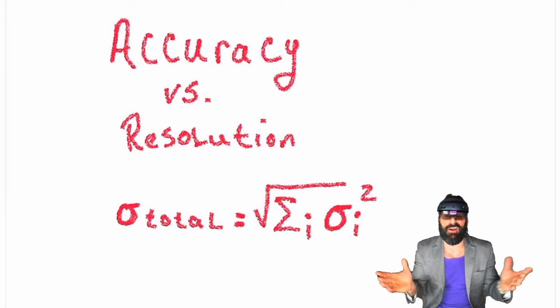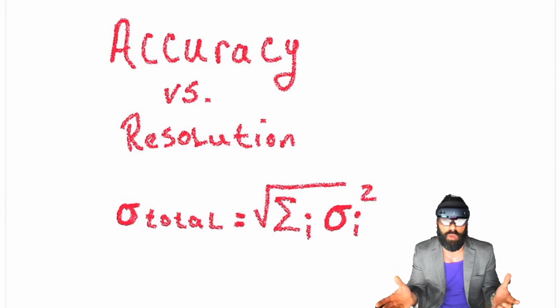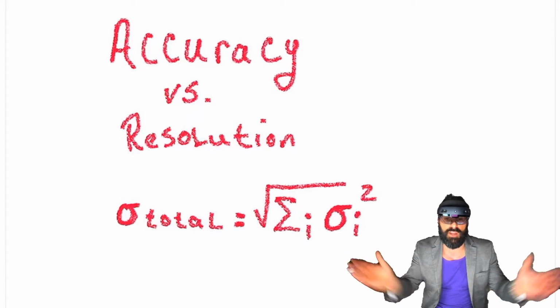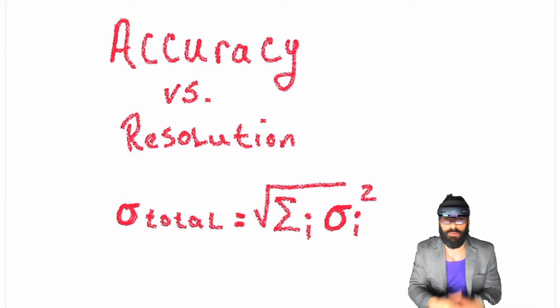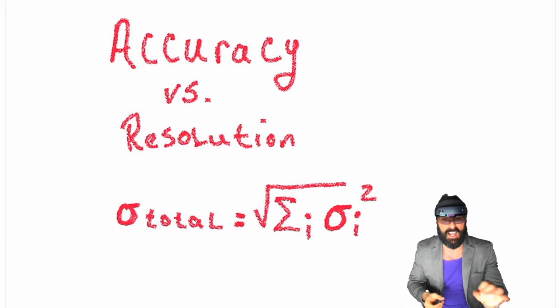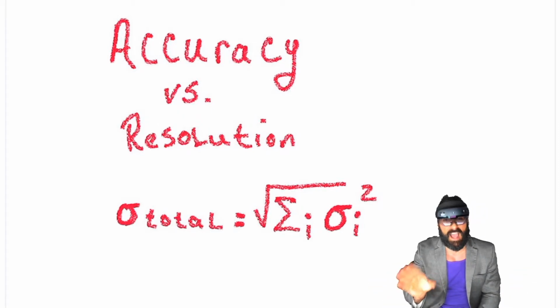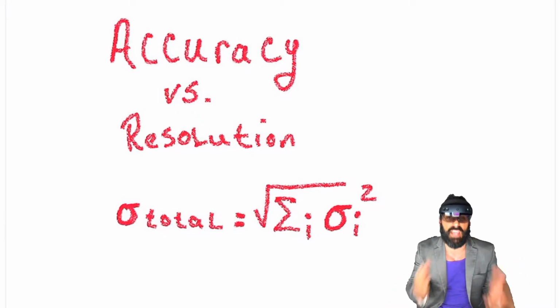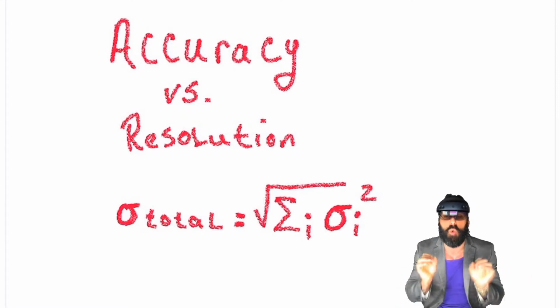Now these ADC errors are typically specified in 3 different ways: the error in the least significant bit, the voltage error for a specified range, and the percentage of the reading error. Now, I'll tell you, this is an honest to God statement. Most ADCs are not as accurate as the manufacturer states, or as is according to their specified resolution, mostly because other errors will contribute to the overall errors, such as gain, linearity, offset, missing codes, again because of quantization, and noise. All of these things need to be taken into account when you're looking at the quality of a product.